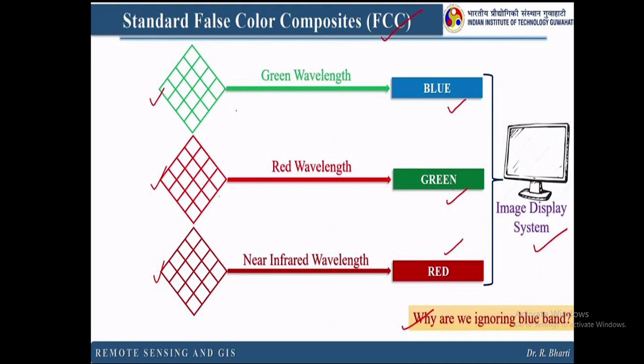So this is the standard false color composite, FCC. In the color combination, blue changes to green, green changes to red, and red changes to near infrared wavelength.